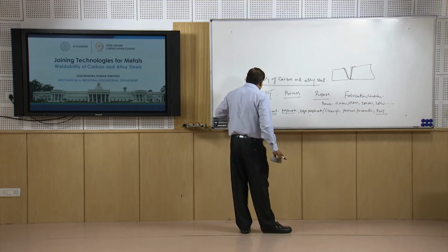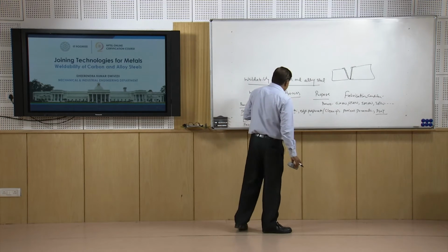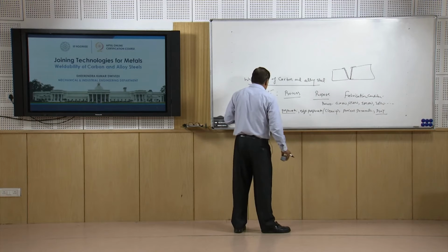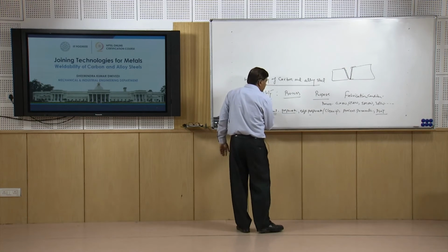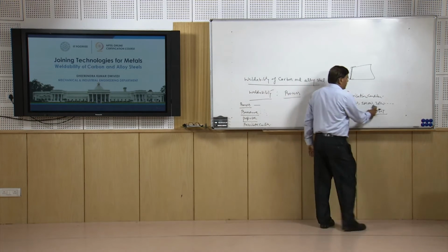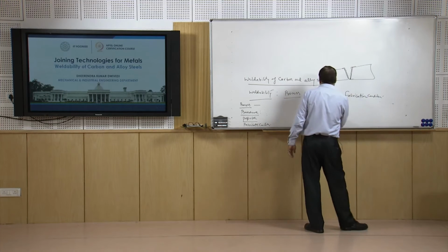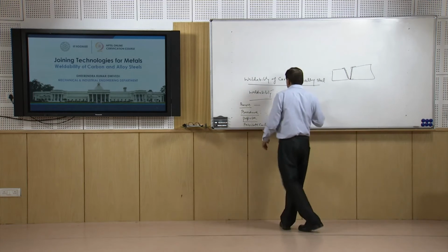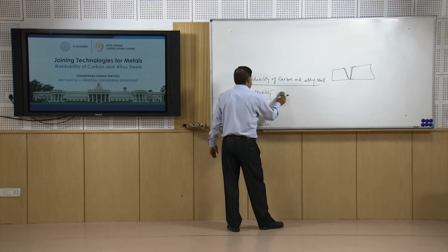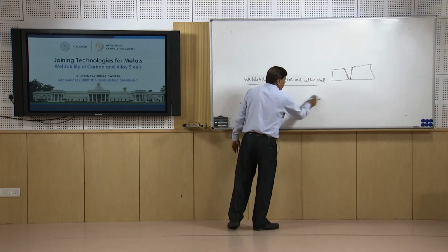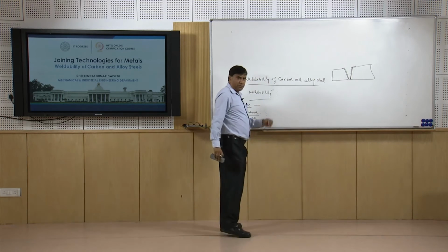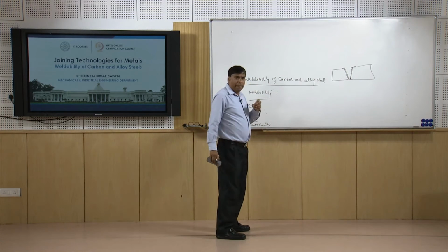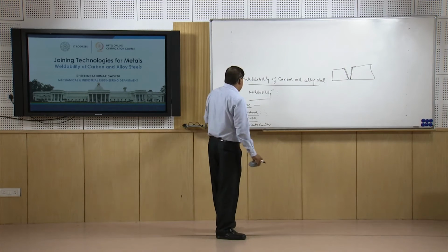So, proper procedure is to be followed for developing a good quality weld joint, and the proper process is to be used. If these are not used, then we will see that the quality of the joint is not up to the mark, or it is full of issues like poor soundness of the weld metal, unnecessary excessive residual stresses and distortion tendency, a wider heat affected zone, etc.